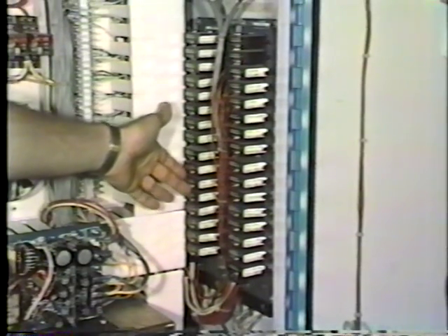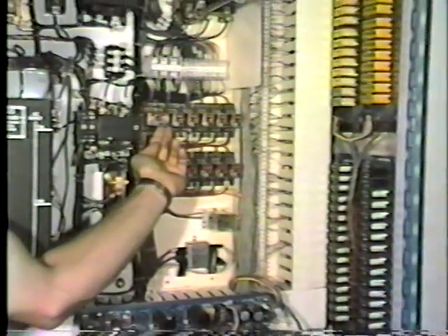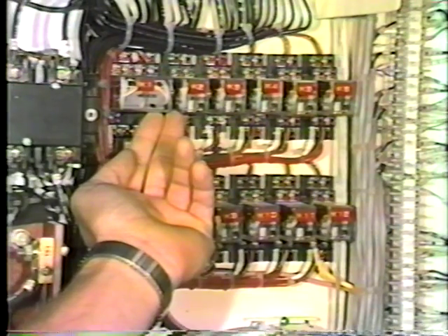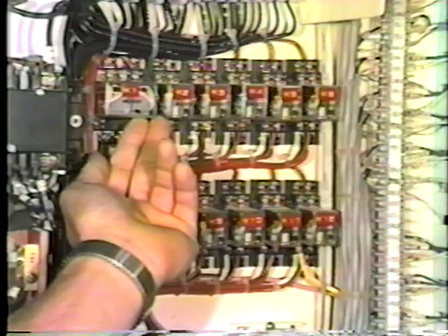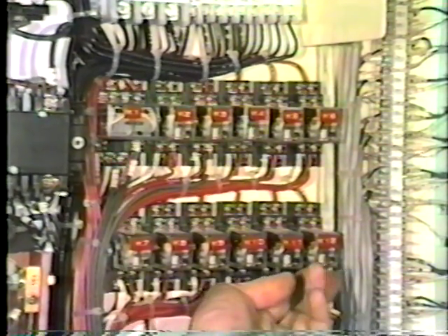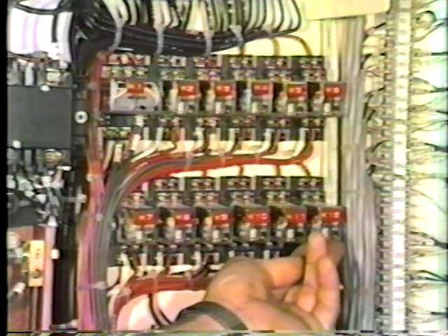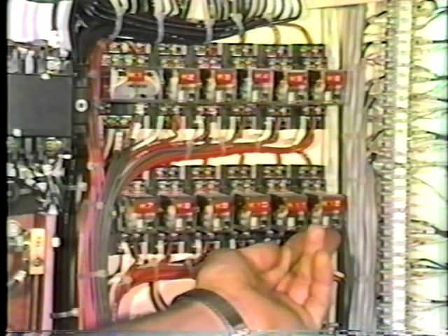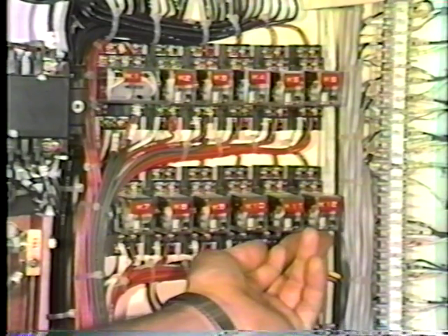Some of our outputs feed hard contact relays, which fire the classifier, pulverizer motor, and exhauster motor. Those are labeled K1 through K12. So those are relays? These are hard contact 10 amp relays. These relays are being interrogated by Forney and also starting the appropriate motors.